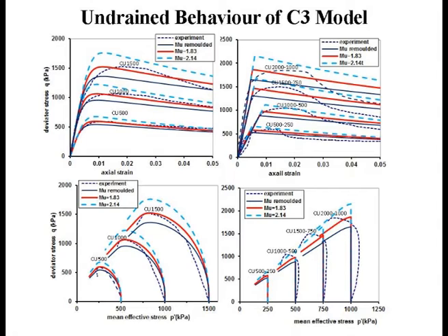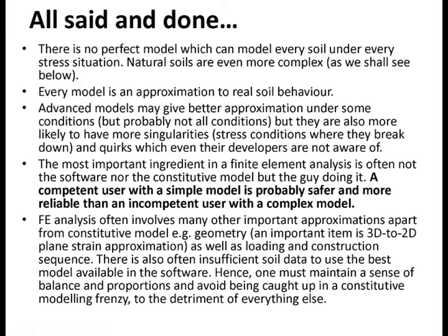Okay? So this is roughly how you can tell a structured soil from a heavily over consolidated soil. Heavily over consolidated soil will show you a stress path that goes that way, or goes up and then comes down this way in a drained situation. In the undrained situation for structured soil, you see something like that, that is quite likely to be structured soil. So the stress strain curve itself may not be telling. The stress path may be more telling.